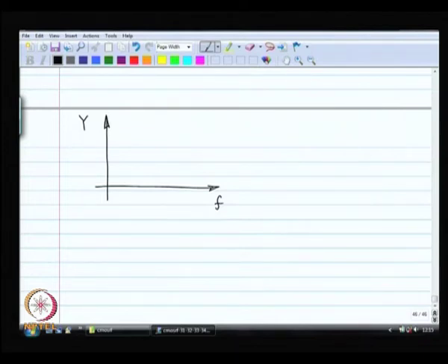now let us put a sampling frequency over there and say it is a discrete time system, all right. So, this is your Fs by 2. In our case, we have a discrete time system. The restriction for the sigma delta or delta sigma converter is that the input is a low frequency signal. It is not changing as fast as the sampling rate. In fact, it is changing much slower than the sampling rate.